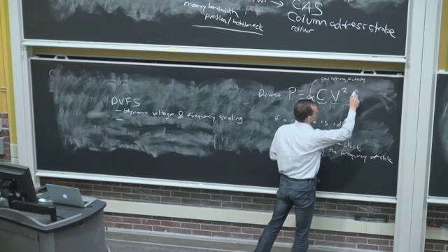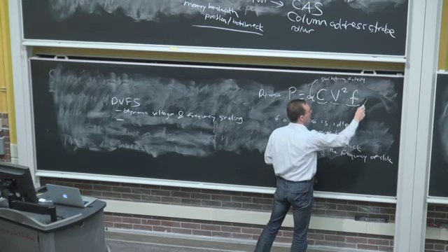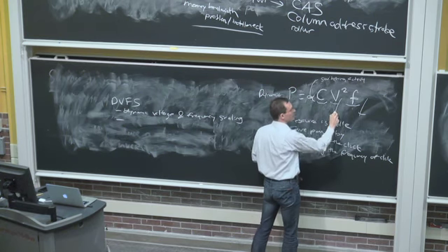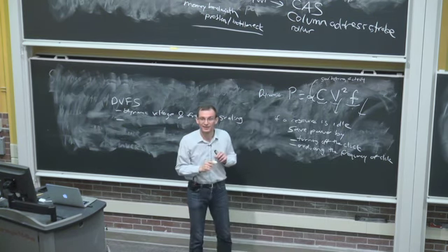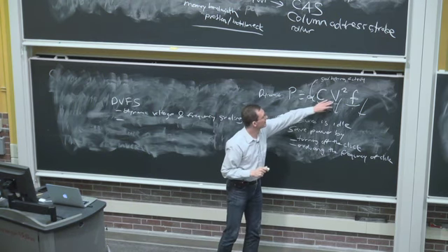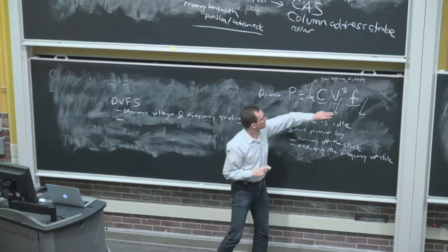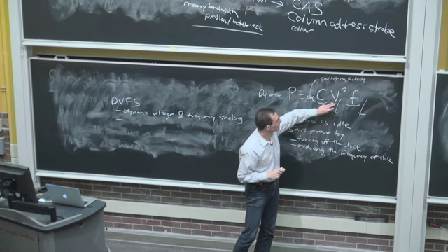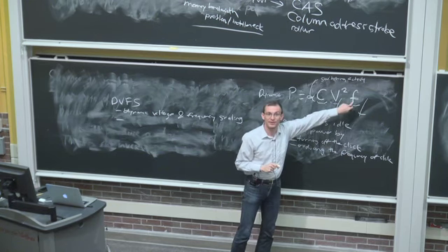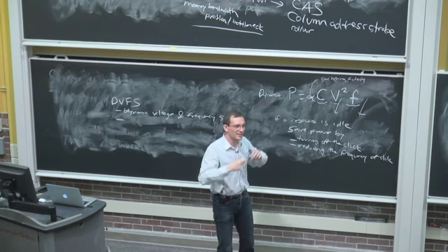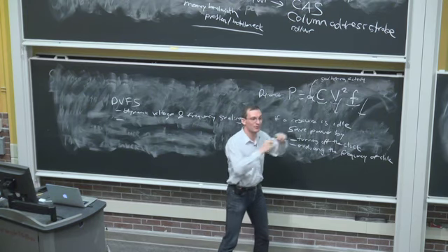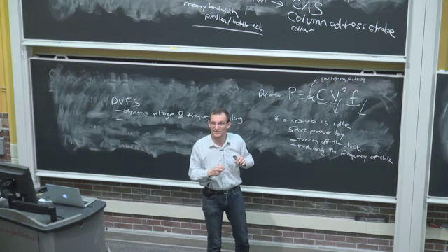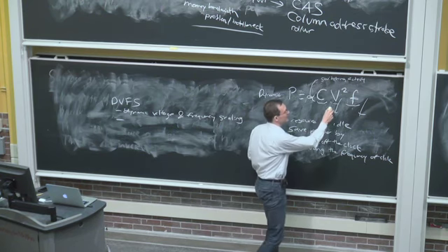And frequency, if you reduce the frequency, your power goes down. If you reduce the voltage, your power goes down quadratically. Now it turns out in existing designs, you need higher voltage to support higher frequency. So when you don't need higher frequency, you can also scale down the voltage. It takes more time, but you can do that in existing designs.